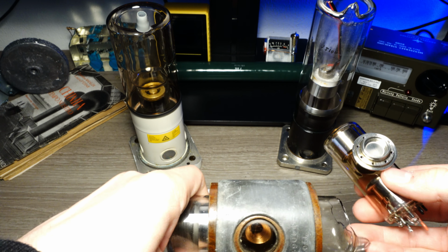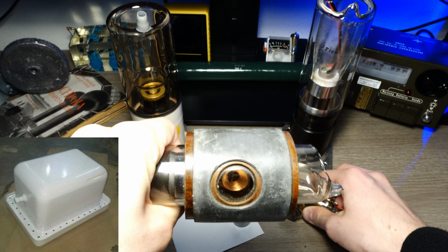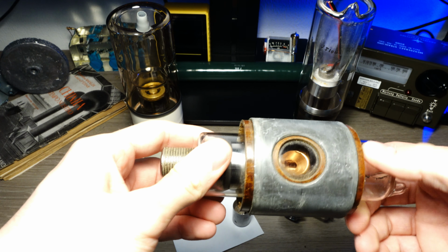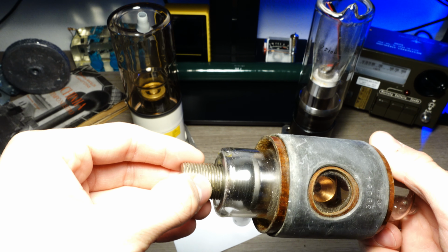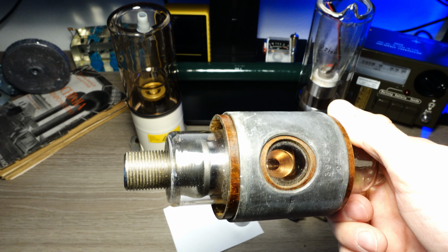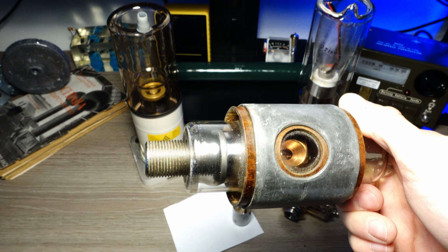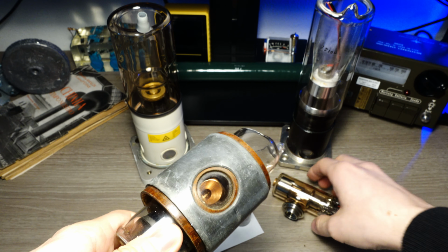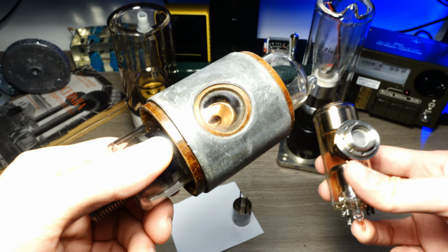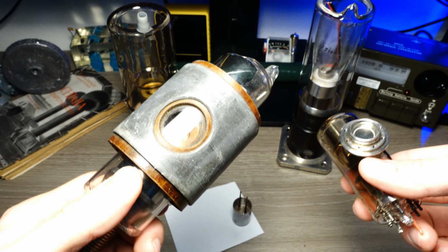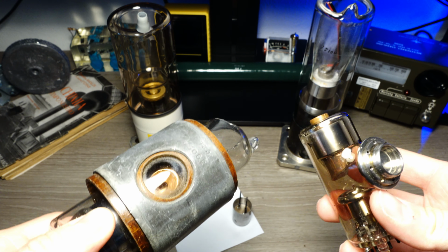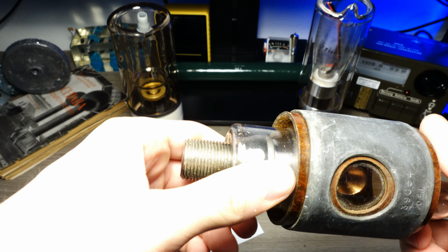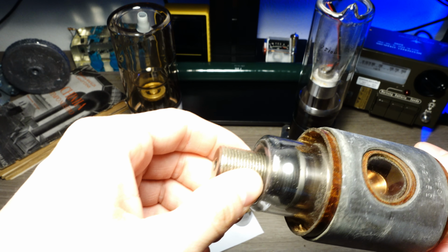So both of these tubes will normally be placed inside of an oil bath with an aperture to let the X-rays through. And so the heat from the current flowing through the anode will be dissipated only through the conduction between the metal and the oil itself. And for this reason, these tubes normally have a maximum power rating of around 300 or 400 watts. This little tube is probably a lot less, like in the tens of watts, while this bigger one may be up to 200 or 300 watts.